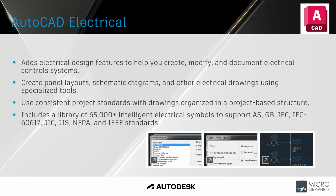One of the great things about this is that it can create a bill of materials, missing bill of materials, component wire lists, from, to. And PLC creation: you create PLCs, DIN rails, panel layouts, and you can tag them, and there's automatic wire numbering. Oh, that's absolutely great. Automatic wire numbering just runs the whole project. You don't have to worry about it. So if you guys are doing AutoCAD electrical drawings, get into this. It's a great package.